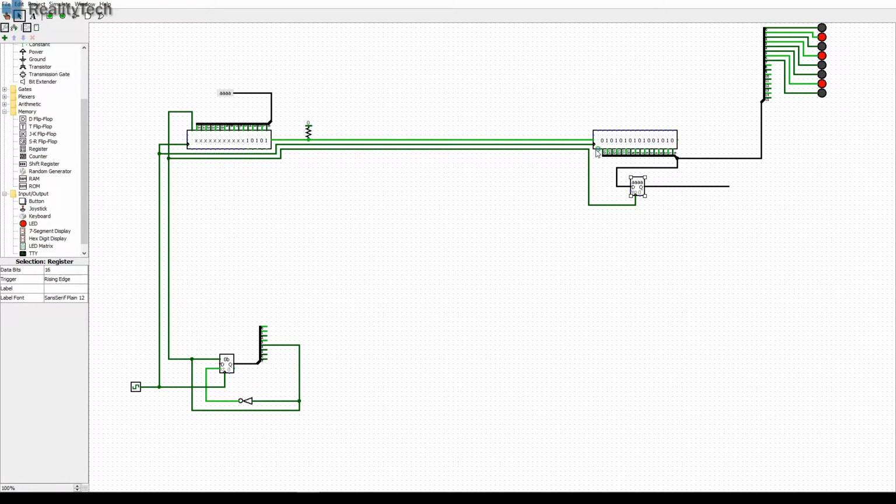And when we get our reset, let's just pop that in because that will reset the counter to 0 as well. That also helps stop some of the silliness. And you can see our 8 bits are still shifting in. But if we now break this and feed it from our register, you'll see that we're not shifting.